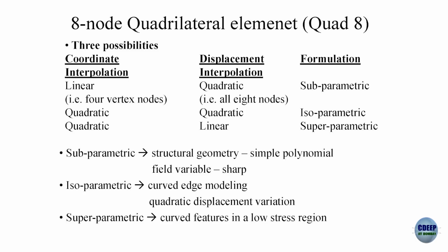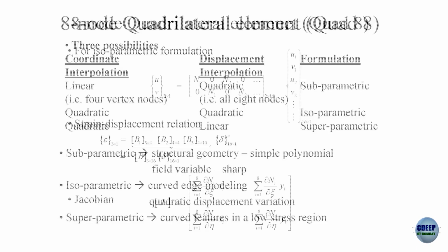We have already discussed this idea of whether I should use subparametric or isoparametric or superparametric. What we discussed at that time was that there are two things that I am doing interpolation for. One is the coordinate transformation, another is the field variable variation. If both are done using the same set of shape functions, then it will be called isoparametric. So we recognized that there could be subparametric and superparametric elements, but we limited our focus attention to isoparametric elements. So I will go further with only isoparametric formulation.